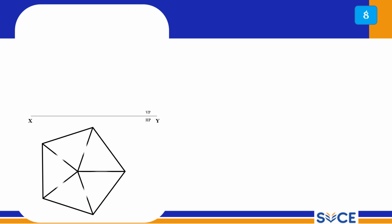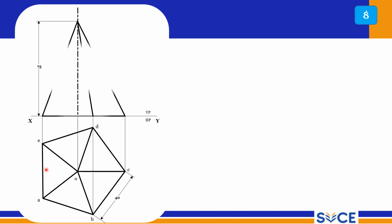So this is the pentagonal pyramid. The orientation is given: one of its base sides is perpendicular to VP, and this is the simple front view. Draw the cutting plane. You have to cut the plane at 30 mm from the vertex, at 30 degrees. It is passing through 30 degrees. Now this is an inclined plane.